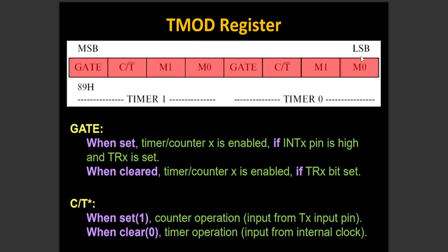When in this mode, at least two machine cycles are needed. That is, when the frequency is 12 MHz, the maximum count frequency will be 12 MHz divided by 24, that is equal to 500 kHz. So, for event counting, the time duration is 2 microseconds.